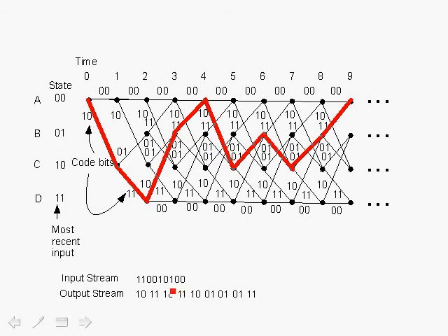It is not good for bursty errors in which many adjacent bits are in error, which typically happens in a multipath channel when, for example, one carrier runs into a deep fade. But there's another error correcting method called Reed-Solomon, which is a linear block code, and that corrects bursty errors and usually can be used in combination with a convolutional encoder and a Viterbi decoder as the inner forward error correcting code, and the Reed-Solomon would be used as the outer.